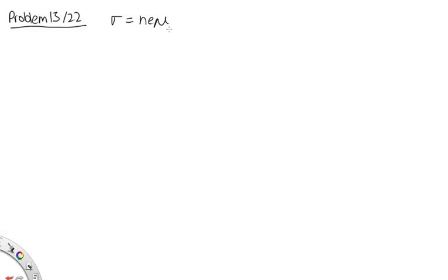In a particular semiconductor specimen, there are both N electrons and P holes per cubic meter present, and the holes have a mobility mu_H. Write down the expression giving the total electrical conductivity due to electrons and holes.